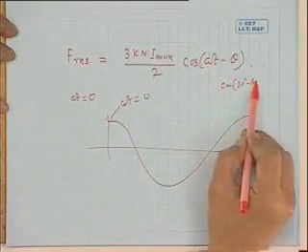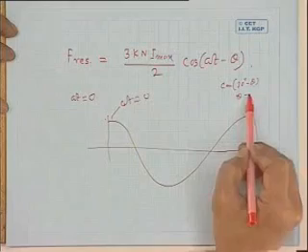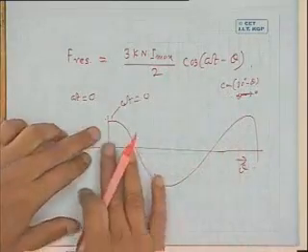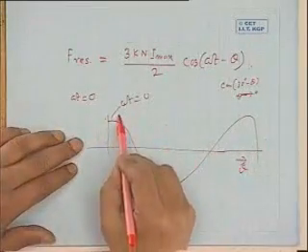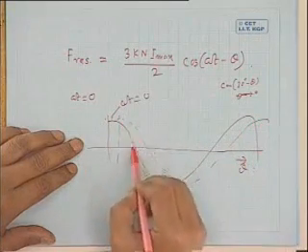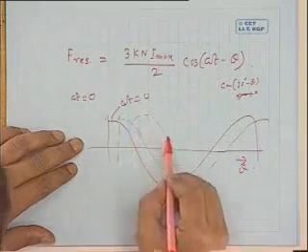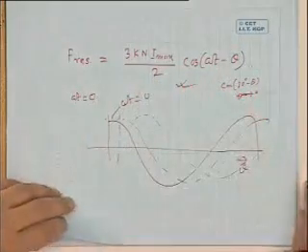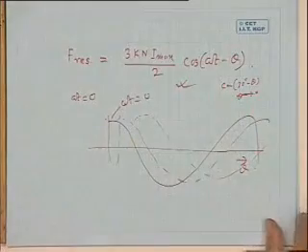See, omega t equal to 30 degree. This will be cosine 30 degree minus theta, meaning cosine of theta minus 30, same thing. So it will once again be a cosine wave with respect to the first one at omega t equal to 0. It will move by 30 degree. At omega t equal to 60 degree, same distribution but shifted towards the right. Therefore, it represents a traveling field moving from left to right, and I will discuss in greater detail. Today I did it slightly faster, next class.